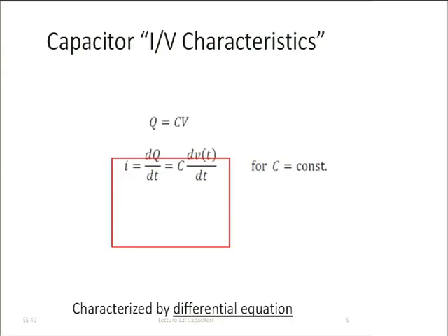What happened here? Well, somehow this decided to sweep down a little bit. But anyway, we have that top law that we talked about. That's kind of Ohm's law for capacitors. Now, there is something a little funny about that. Instead of relating voltage to current or current to voltage, it actually relates charge to voltage, right? But we can fix it very easily. What is current? Well, it's simply the amount of charge that passes per second. So it's dQ/dt, right? And so if we take the derivative on either side of this equation, we get dQ/dt, that's simply the current, and that is equal to capacitance times the change of voltage, okay?